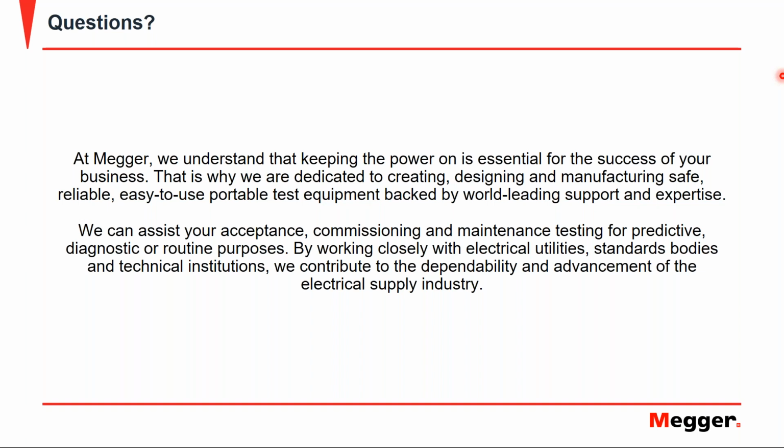But for aged cables, it's all experience from manufacturers and from utilities, which is summarized in tables that can be used as a starting point, and then the customer should build up their own database. Normally, looking at XLPE cables again, if everything is PD-free up to operating voltage, it's a good sign. If there are discharges at operating voltage, there's always something burning within your cable, so the risk is higher.